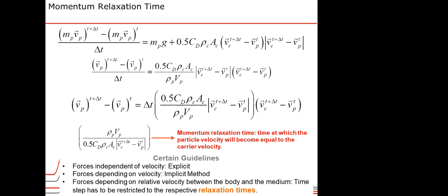And also, when we do a simulation, the time step that is selected for the simulation should be based on this relaxation time. Because if you want to capture what is happening during this process, then the time step has to be less than the relaxation time. But in most off-the-shelf softwares nowadays, there are methods to calculate the relaxation times to some extent, and they use these times to calculate the simulation time steps automatically.